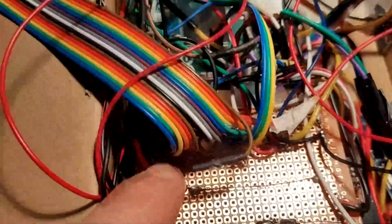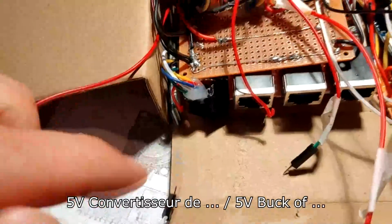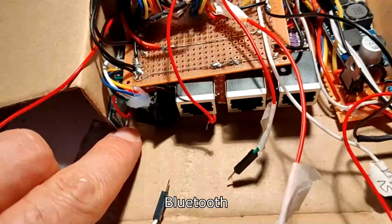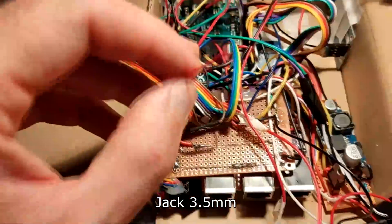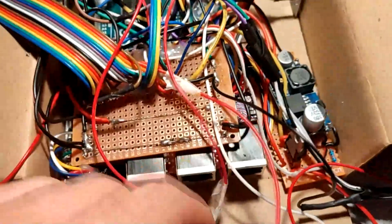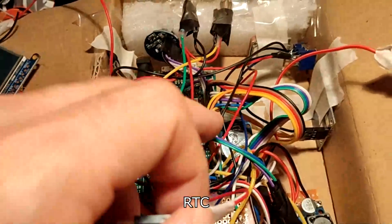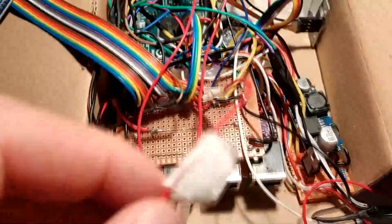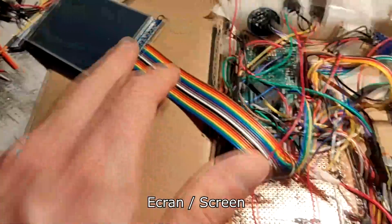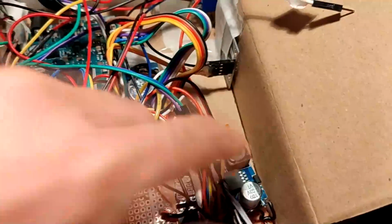Here is the first one coming from the speaker. So now I'm gonna link all the 5 volts buck wires, the Bluetooth module. This one coming from the jack connectors. This one is for the RTC module right here. This one is for the screen, and all this stuff will be connected to this wire, which is the 5 volts buck power supply.